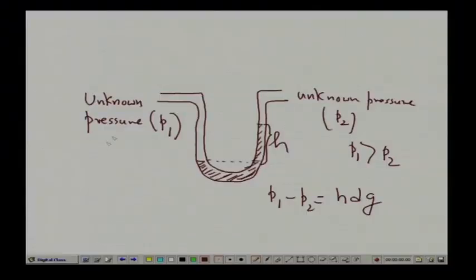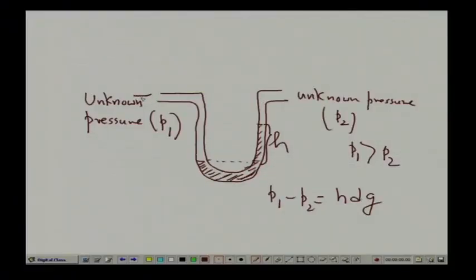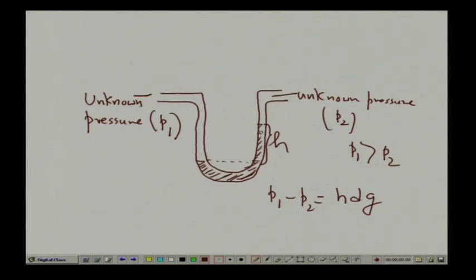Now, you can make it colored. If you put some color, you can use water as the manometric liquid. Now, there is another problem: the actual fluid which is coming, if it can get in contact with the water and reacts with the water, that creates a problem, because the P 1 which we are measuring and P 2 will be connected to some liquid or some gas. That gas or liquid should not react with water, so you have to prevent that, otherwise it will create problems.